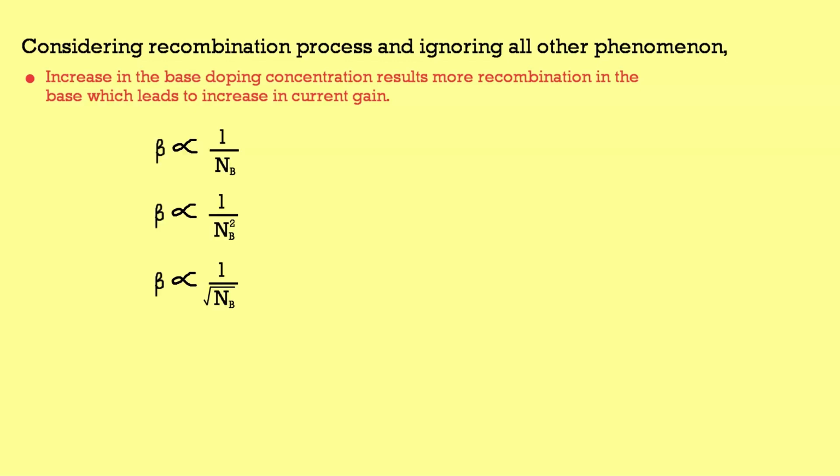See these three examples. For all these three cases, we can say the common emitter current gain will increase as the base doping increases. In electronic devices, temperature also plays a significant role. Like there is no single formula for band gap energy which is valid for all the temperatures. It deviates at very high and very low temperatures. Even the ideal diode current equation deviates at high and very low voltages. It may be possible that the three shown relations may be valid for different temperature ranges, but a simple and straight mathematical relation cannot be formed valid for all temperatures.